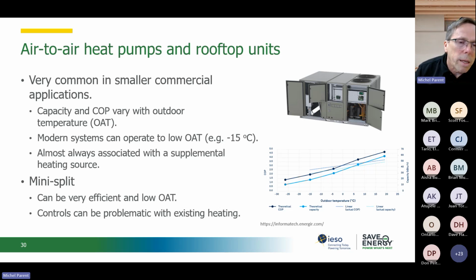And they are limited in outside air temperature under which they can work in heat pump mode. Typically, at about -15, they will switch over regardless of the peak of your building. Below that, you can keep them working, but their COP really drops and their capacity really drops. So you will not have sufficient heating capacity. Again, it's often a capacity issue that will catch up to you when you go too low with the heat pumps.